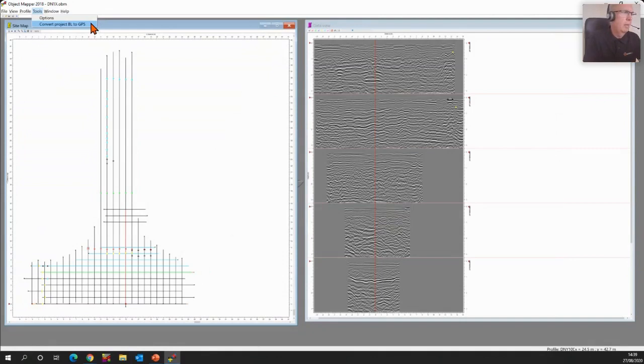Or what sometimes I do, I export out the DXF and just rotate it over into place above the line that I've collected with the total station, and just fit the actual baseline into the right position, and then all the offsets for the markers will be there also. Okay. Like I say, finally, you've got the user manual option at the right hand end, and there's some good hints and tips in there as well.